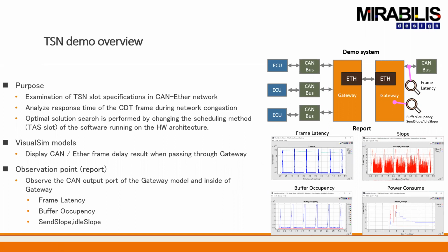One of the key things within time-aware shaping is the scheduling method. So it's important to take the scheduling method and be able to modify it in such a way that, one is, the hardware has sufficient processing capacity that it can handle the scheduling algorithm. A lot of times, algorithms are great, but because the hardware is not able to handle the workload of the software task, you get a completely different profile. So it's important to realize what should be the hardware processing.